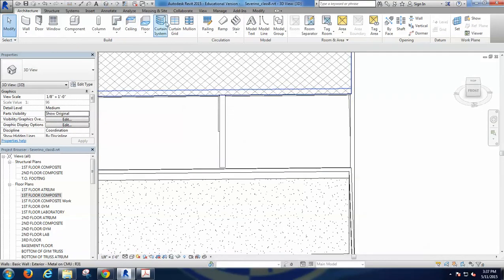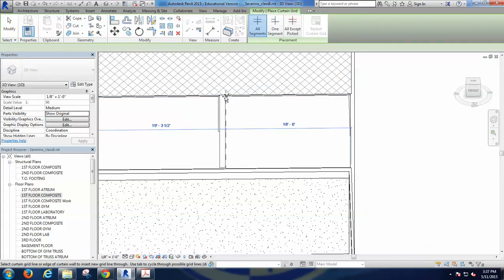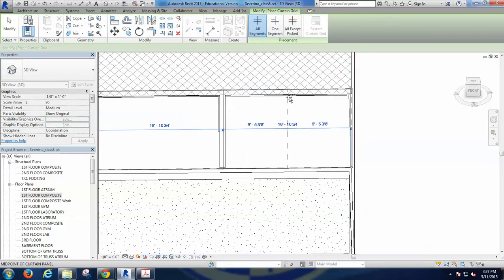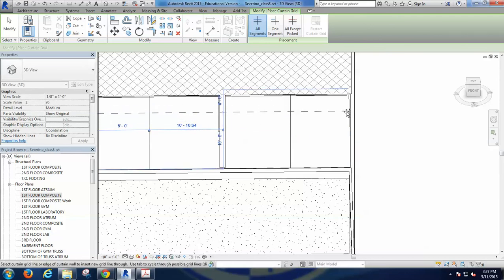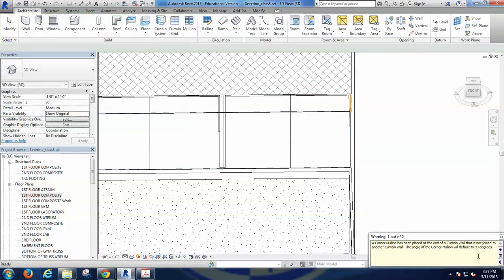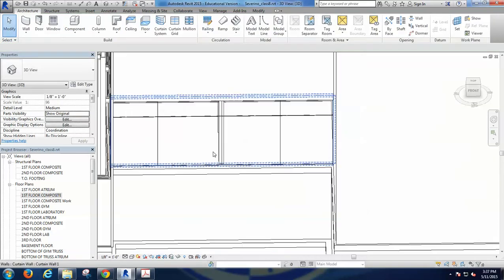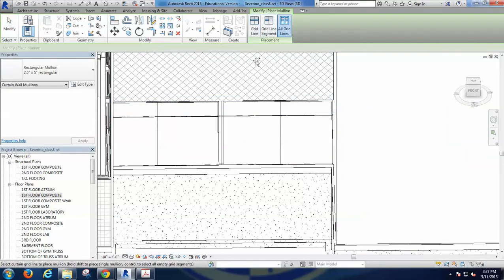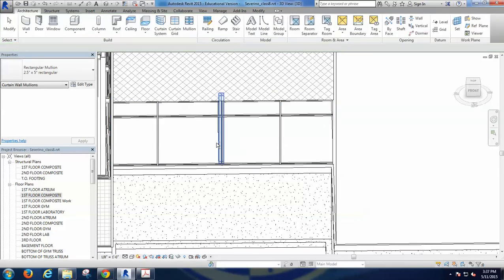Last we're going to put a couple windows there, but if we want to place, again, we can go to the curtain grid and place a couple grids, like center and to different distance, same distance, and then a horizontal one at 10. And here's where you can again select mullions, say all grids, select grids. So there you have your mullions.